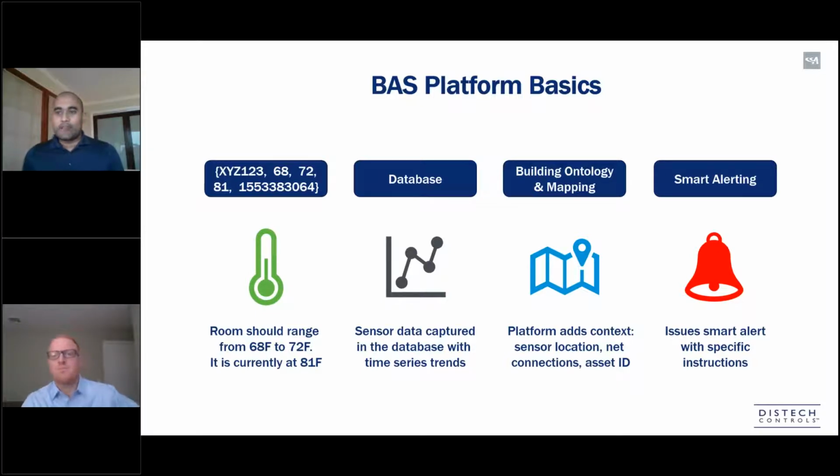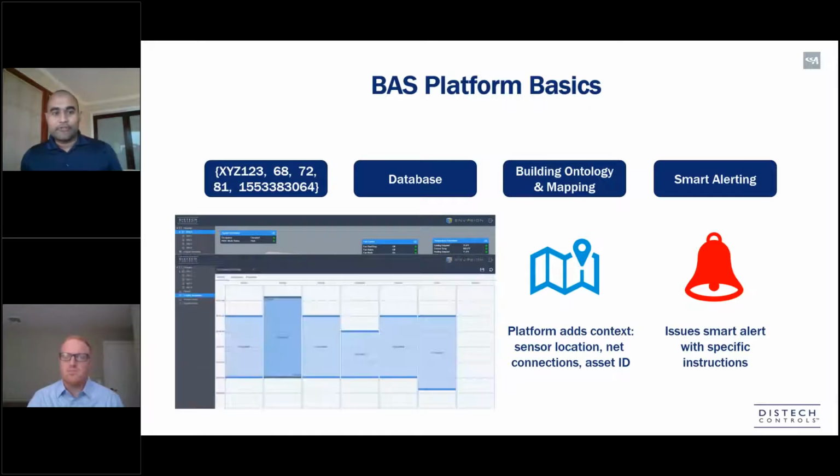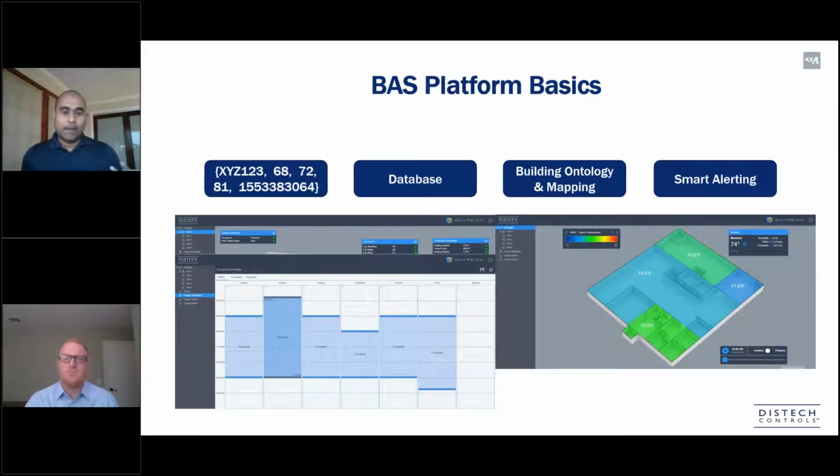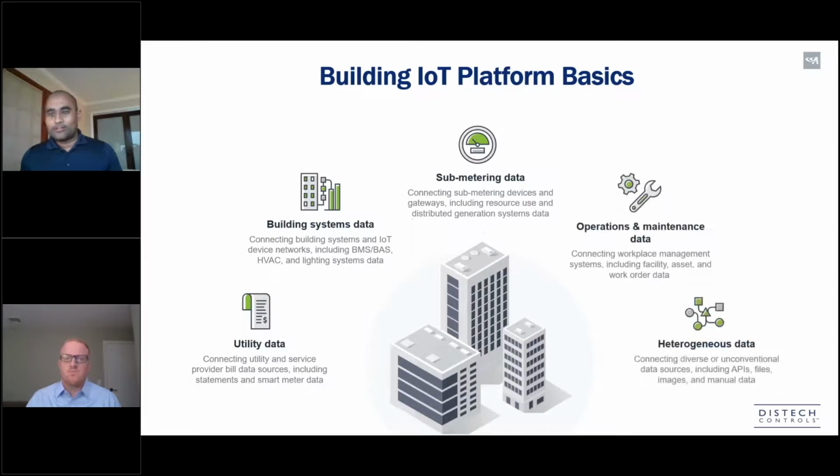It's important for a building manager to see graphically what is happening in the building. So all these data sets and data points have to be mapped onto a good, easy to navigate graphical user interface, whether it's to change set points, to do scheduling, or to pick out maps of the floor spaces and relate data to different parts of that building, and ultimately a good and clear alerting system that they can easily see, understand, and acknowledge.